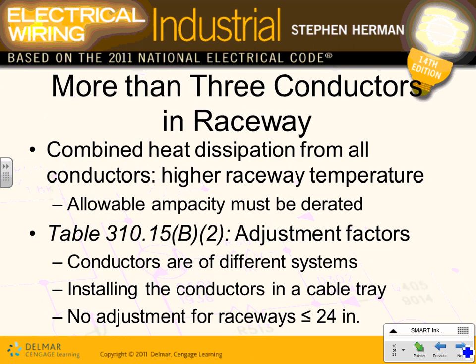Three conductors in a raceway. If you put more than three conductors in a raceway, Jeff, what do you do? You derate them. I know by now. This is the table that adjusts for derating. Conductors of different systems, installing the conductors in a cable tray, also you have to derate. And the only time you do not derate is if you have a little short run of a conduit, 24 inches or less. 24 inches or less.